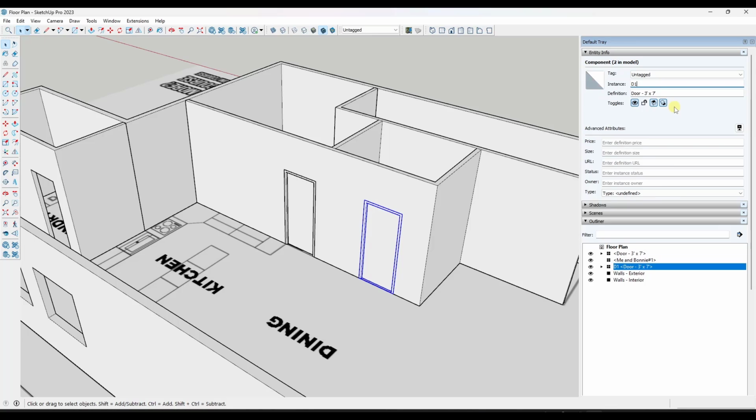We're going to hit the enter key. Notice how when we do that, now I get the D1 in here, and then I get the component definition. So for this one, I would call that D2 right here. And so we can use this to name our doors. Note that if you have more than 10 doors, you're going to want to call this door 01 and 02, just so that your naming actually lines up in here.